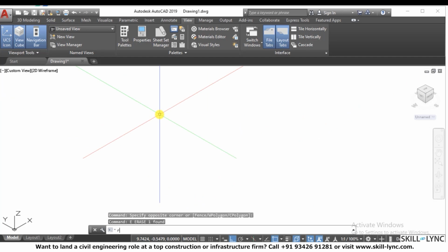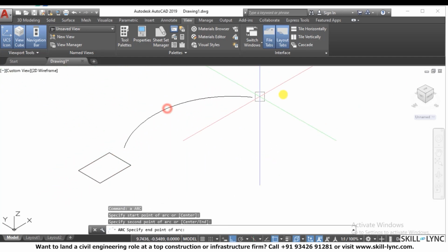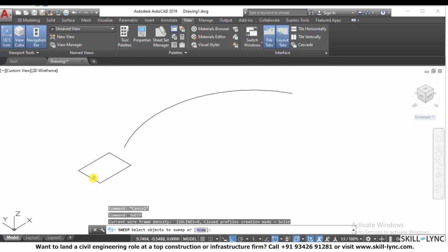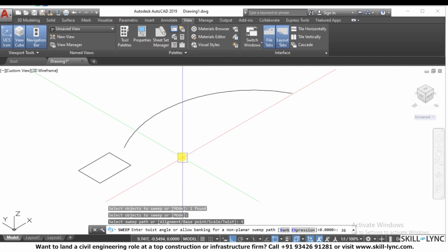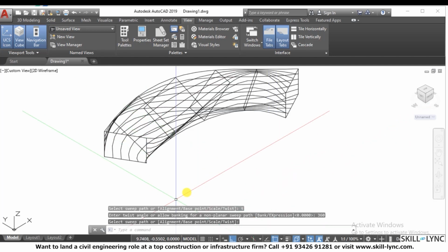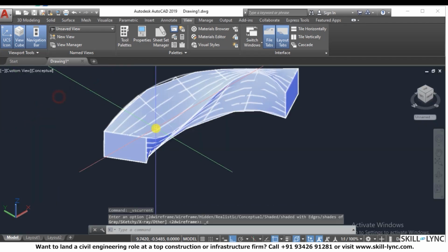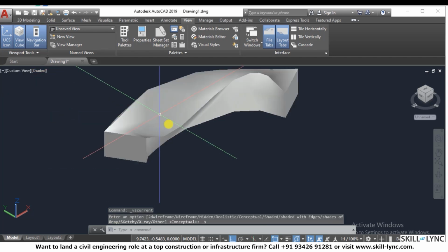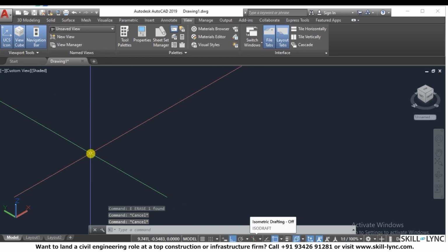So if we were doing a rectangle sweep, at least the twist option. So we have this sweep, select the twist option, let's say 360-degree twist, the path, the object gets twisted. So you can have the shaded portion on, and you can see how the twisting is done. So this is the sweep option that we have discussed.